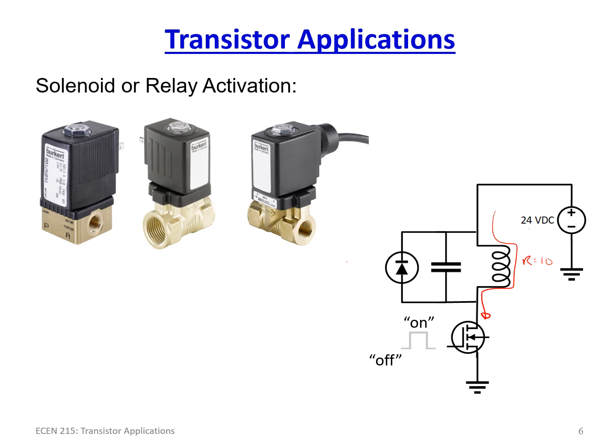And so it will generate what is known as back EMF. And so it will generate a reverse voltage here, which is going to affect your power supplies and your digital electronics that is controlling this. So to prevent that, you put in a capacitor here.